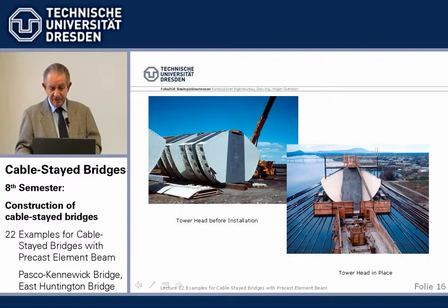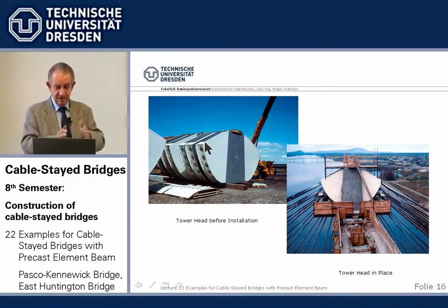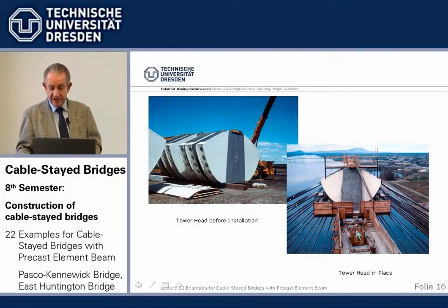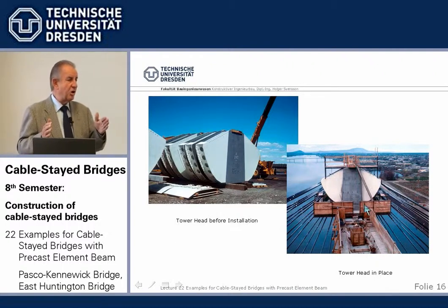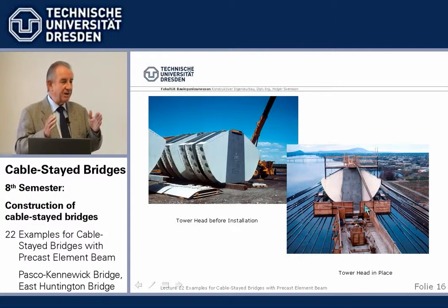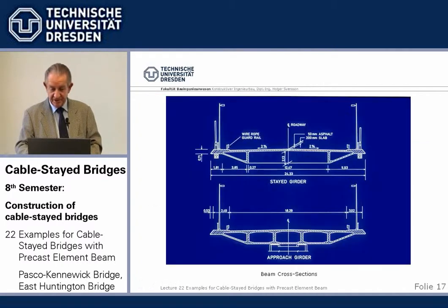The tower, as I say, we had 3 stay cables, one beside the other, and they were delivered in 3 slices, I may say, pieces, lifted up by crane, installed. The cables here are already in, and then the concrete tower was continued up around these steel boxes. We used to call them concrete ears, where the steel part is our head, and the concrete ears, a little bit bigger, make it composite with the tower.